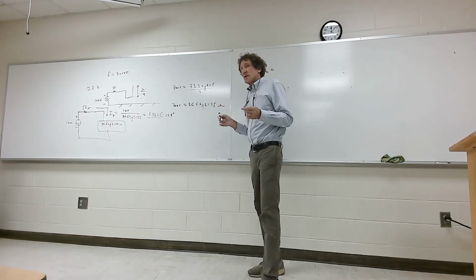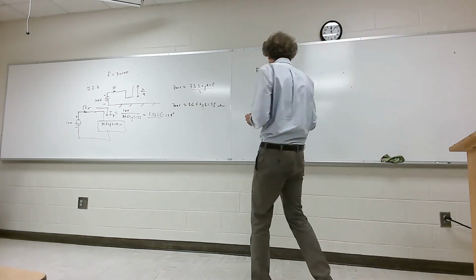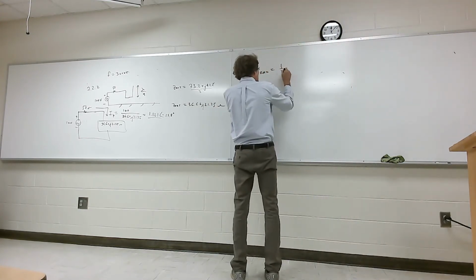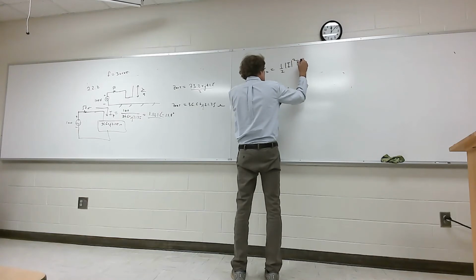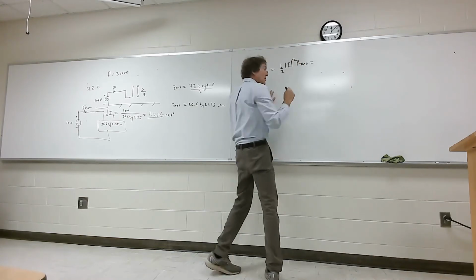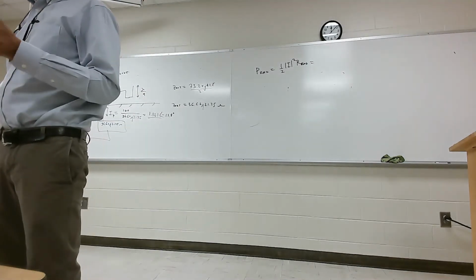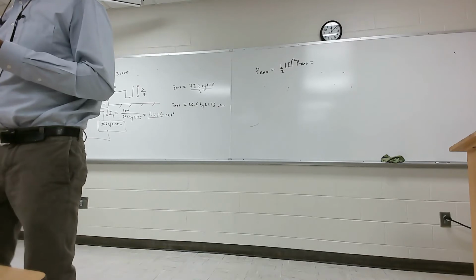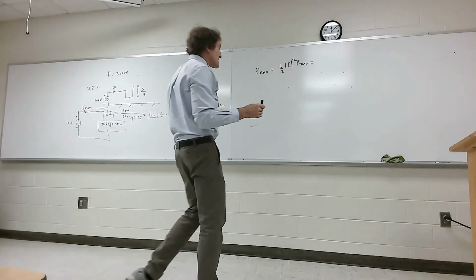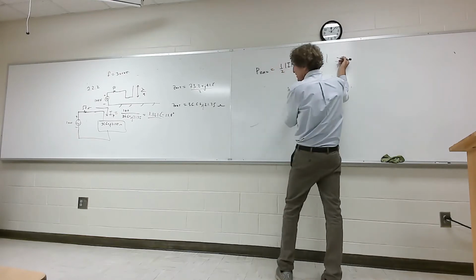What is power in general? If you just had a resistor and you knew a current, hint. So what? 1/2 magnitude of the current, right, squared times the resistance. In our case, it's the radiation resistance. Y'all follow me? What is the radiation resistance for this one? 36.6. That's right. It is the real part of the antenna impedance. It's 36.6 ohms, right? So this is going to be 1/2 times whatever that is,